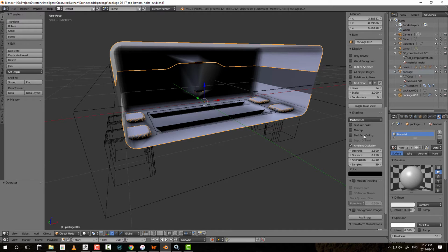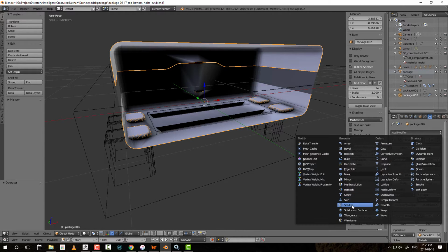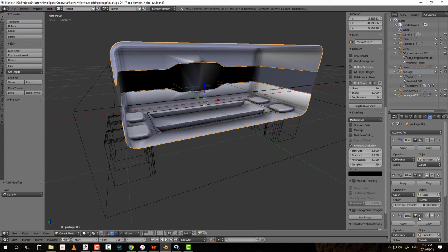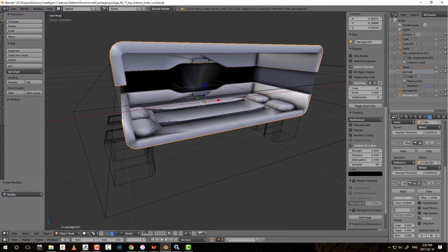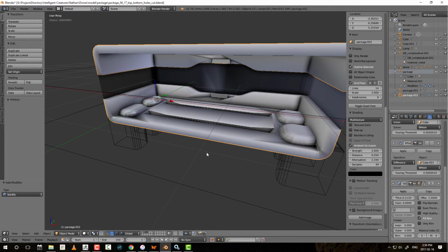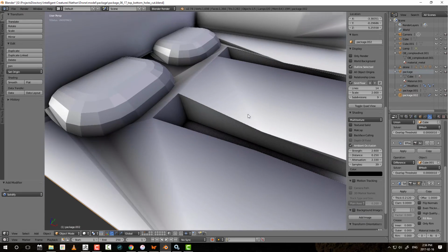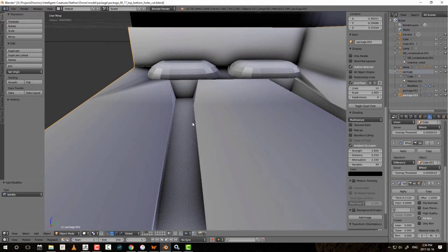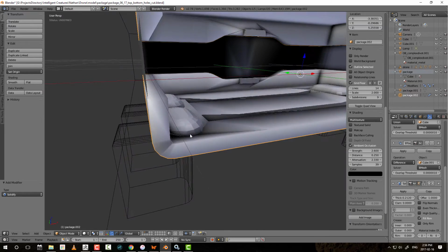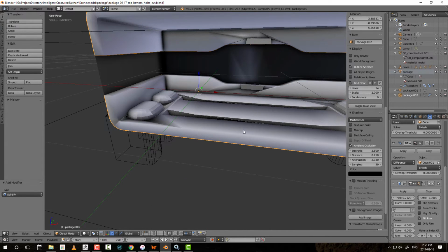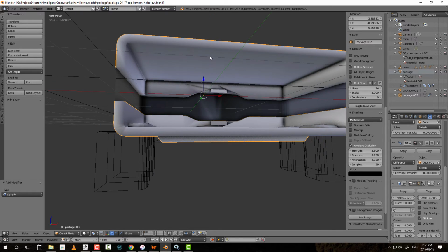so follow my mouse, all over to the modifiers, and I add a modifier called solidify, you'll see this go to the bottom and apply some actual thickness. And let's just say I want the wall to be about that thick. I guess that's okay, but it starts to kind of fall apart in some areas, right? This is not exactly what I wanted. It gives some pretty ugly results. And quite frankly, I don't want any of these shapes to be on the inside, or these keyholes either. So what can I do?